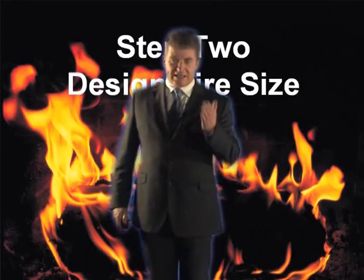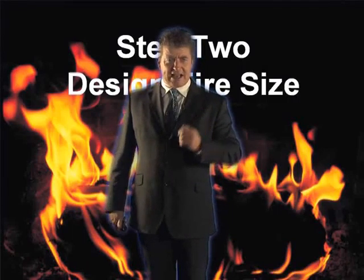Step 2, your design fire size. You've got to determine the design fire size to be adopted. Now we're told that it's standard response sprinklers that are to be installed, and again the convention to use for standard response sprinklers in this case is a 5 megawatt fire with an area of 9 square metres and a perimeter of 12 metres. This is the general design fire size for a building fitted with standard response sprinklers.